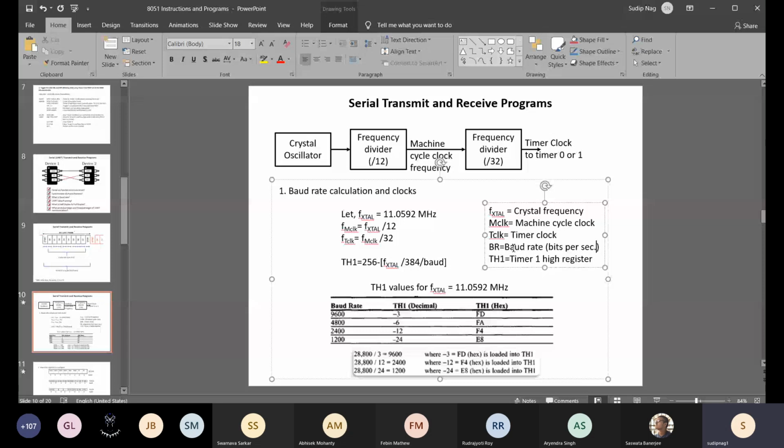because of the standard set by the companies since the 1970s or 60s even. UART was originally developed by Hewlett Packard, HP, the guys who make printers. At that time it was not called UART, it was called simple serial communication protocol, because there was no other competitor available. This was one of the very first serial communication protocols. They developed certain fixed bit rates, and that's what we are still following even today. Most modern microcontrollers also follow those standard baud rates. Obviously, the higher limits have been expanded, but those rates are still available.